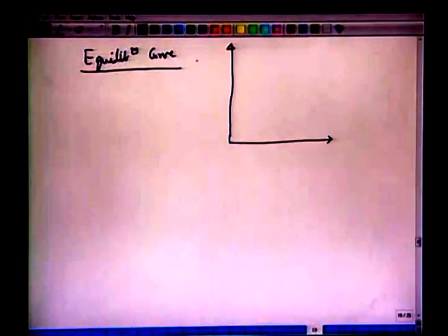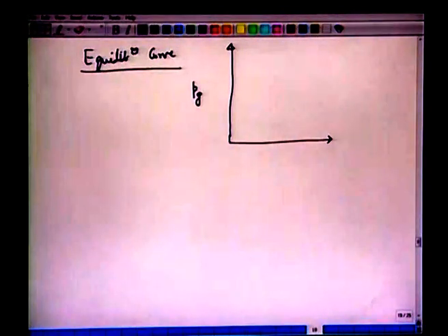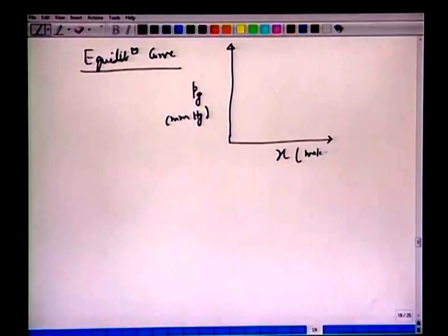because this is our starting point here. Given the partial pressure in the gas phase, say certain millimeters of mercury, how much should x be? So, Pg versus x, or x versus Pg, the mole fraction of gas in the liquid phase.